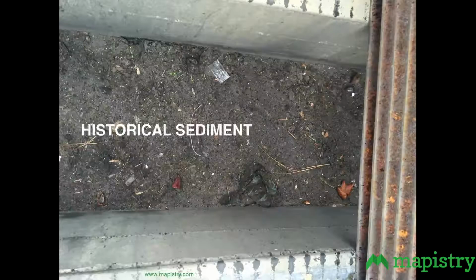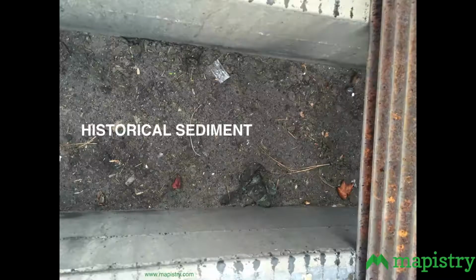The other thing to pay attention to is historical sediments. Even though it may have been a while since you ever popped a catch basin or popped a manhole and looked in there, if you have a lot of exposed sediment on your site, gravel, rock, driveways, parking lots, etc., generally over time that stuff winds up in your storm drain. So even though you might have implemented really good BMPs, there may be something historically underneath those storm drain inserts that's contributing to your TSS issues.